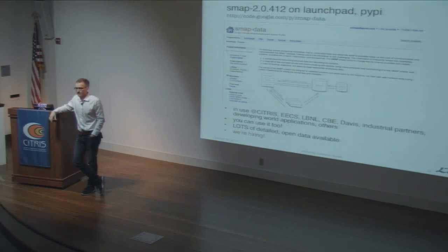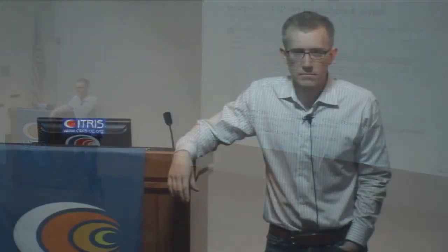Hi. Just a further question on sources. Have you looked into accessing data from building information models or from whole building energy simulation models? Yeah, we have some other collaborators in our group who are looking at extracting higher level metadata that can't be expressed as just key-value pairs from BIM, like IFC models. They're trying to get some Revit models that we can poke around with to get these functional relationships. I agree, there's a higher level of knowledge that you would want even above this, and so generally they've been building on top of this. They take a sMAP feed, which is a time series, and attach it to a point in a richer model for the system.